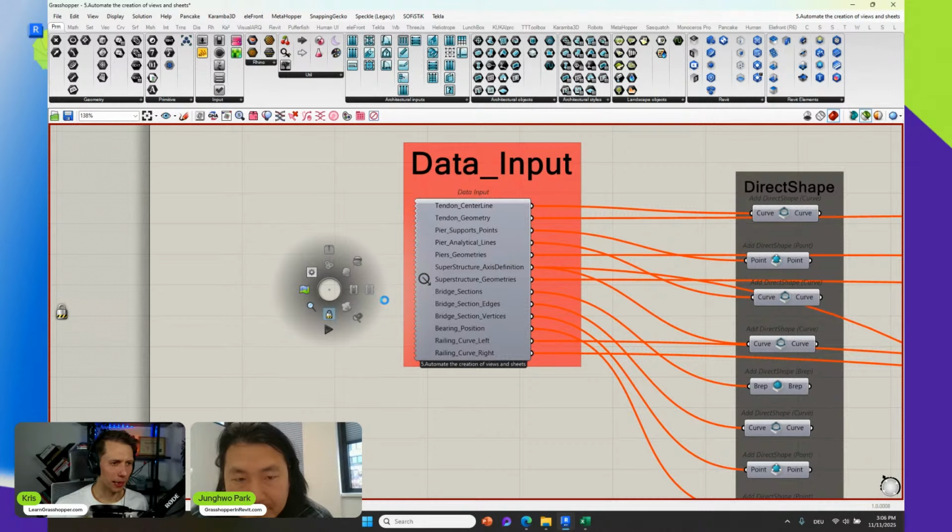By the way, in the meantime, I got a question before this workshop about revisions. Can we make changes of revisions of the drawings through Rhino.Inside Revit? Yeah, it has native revision components that you can use to do all kinds of revision things that Revit allows. Yeah, there is a revision component.